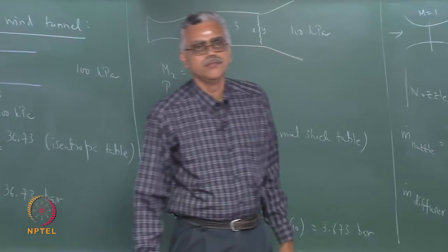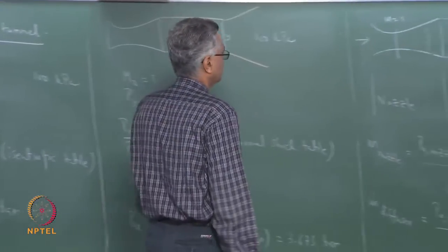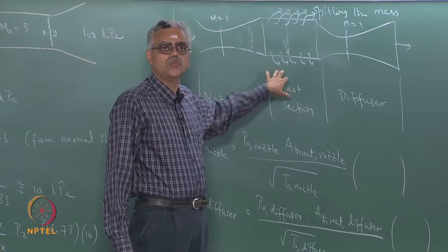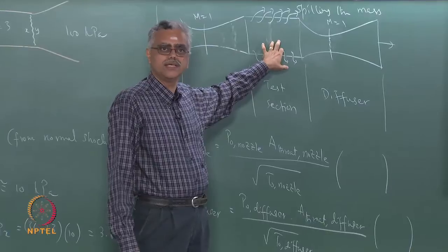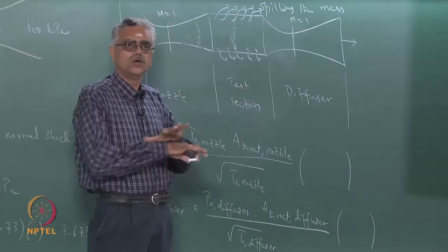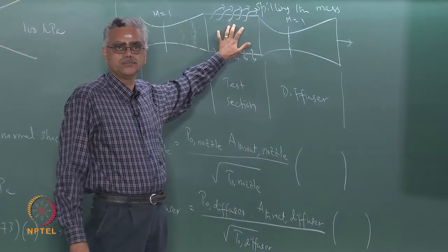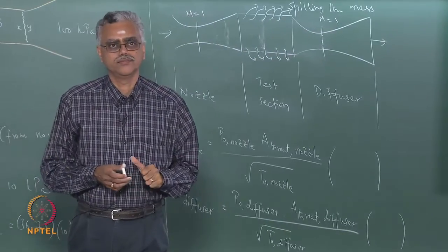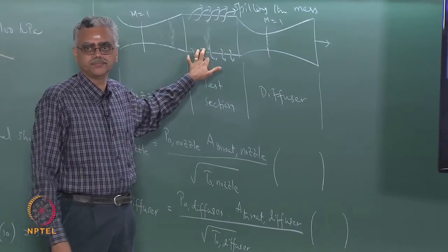Excuse me? They are opening the walls of the test section, right? That's not providing leakages. No. This is controlled bleeding of the flow through the walls of the tunnel. We can actually provide passages like this to bleed the tunnel, and they are closed once the flow is established. You cannot keep them open all the time. You have to close them once the flow is completely established and the tunnel is started. Okay? This is a practically viable strategy which can be used.